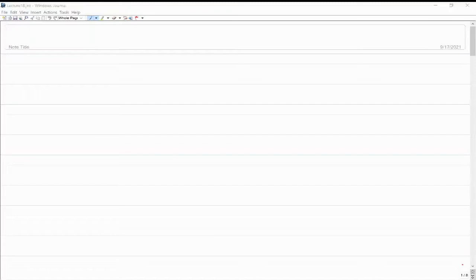In kinematic hardening, yield stress is a function of what? We are not saying yield stress there. In the yield function, we are keeping that term constant, sigma y naught, but the origin of the yield surface is changing. So effectively, the state of stress at which yielding will take place is different in tension and compression.